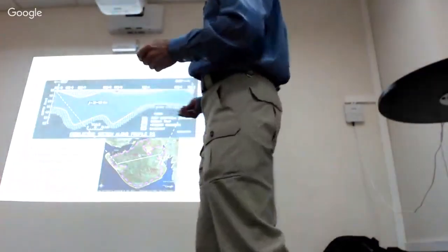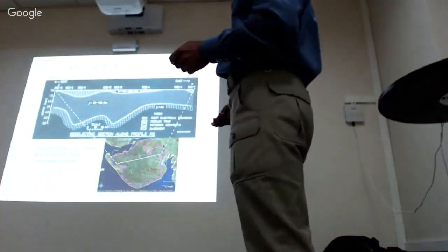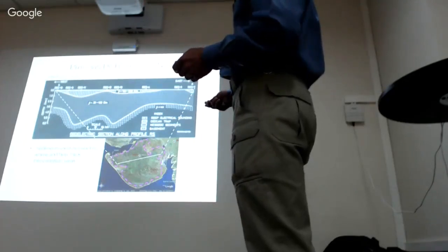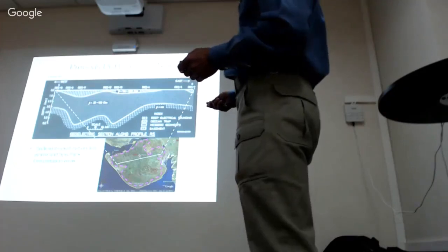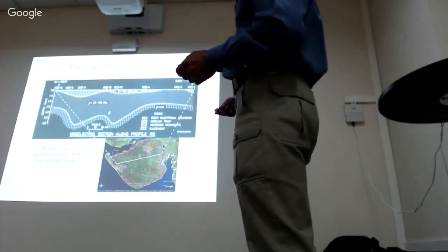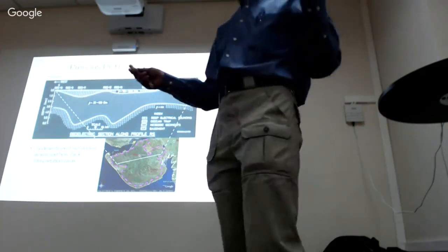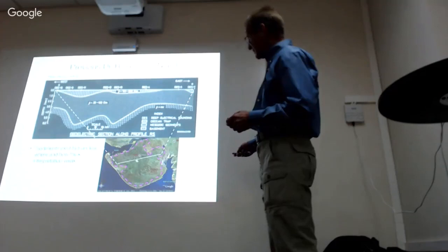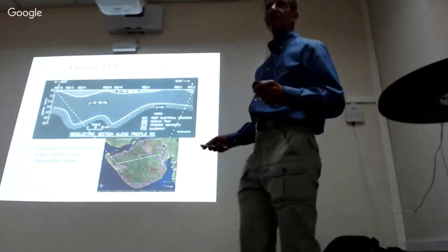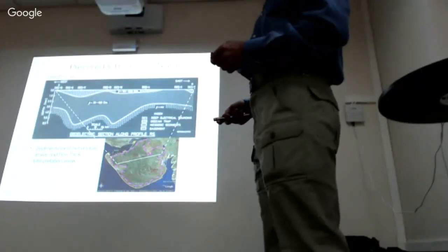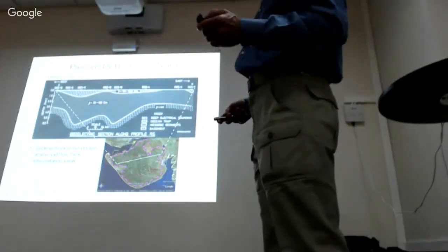There was a survey that was done. It was a DC resistivity survey, went across here. They ended up with a structure that looked like this. This top region was basalt, about 1.5 kilometers thick, and then sediments underneath, and then the basement. That was sort of general. They believed at that time that the sediments were going to increase in thickness as you went from north to south. However, they just didn't know enough, and they weren't really sure about this interpretation. So they wanted to do something else.